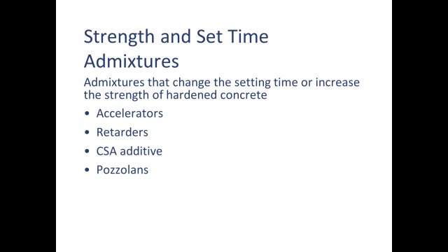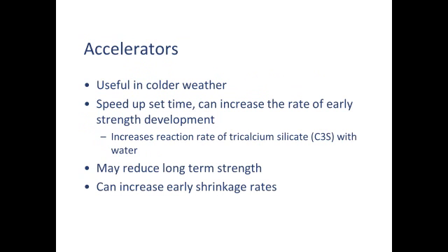The next series of admixtures that I'm going to talk about are used to change the strength of the concrete and the setting time of the concrete. So some of these affect both the fresh and hard properties, and some only affect the fresh properties, or we use them only for the fresh properties, even though they can have influence on the hardened properties as well. So I'm going to start with accelerators, and generally they're useful in cold weather. In the winter, when your shop is cold and you don't want that concrete taking forever to set up, or you want to boost the strength gain of your concrete.